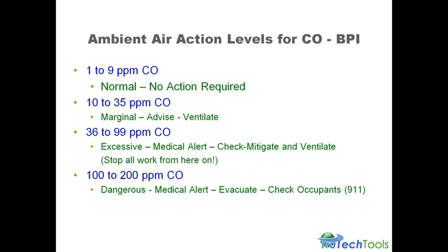If we're producing CO in a home, the problem is how high it's going to go. You might be there on a 40-degree day, and the furnace is running a couple hours a day. What's it doing on a 0-degree day when it's running 24 hours a day? And it may not be the furnace that's causing the problem. It may be the car. On a 0-degree day, your wife goes out, pushes the auto start in the garage, and lets the car warm up in the garage.